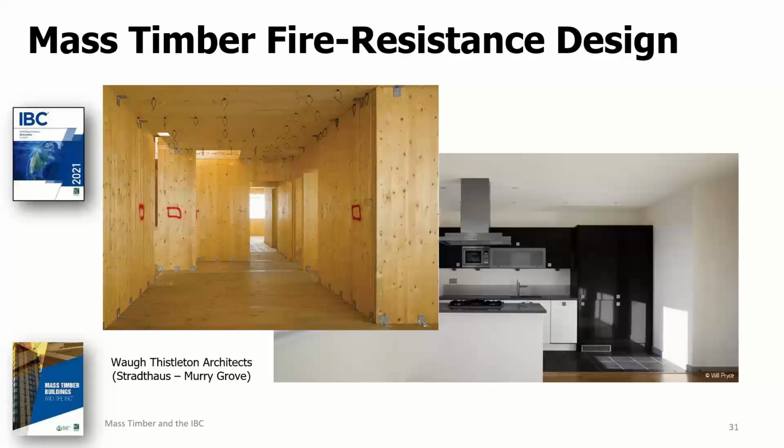As an example, consider a building with CLT walls and floors, like the one shown in the picture here on the left. Say the CLT alone has been calculated to have an inherent fire resistance of not less than 40 minutes based on its thickness and design load ratio.